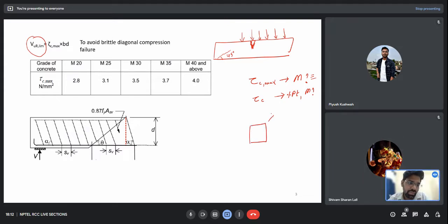Yes, yes. So mainly the principal shear or the maximum shear usually occurs at 45 degrees. That's what you are trying to say. Yeah, that is correct. So maximum shear usually occurs at 45 degrees, and that is the reason we have diagonal cracks like this. That is fine. You can relate with that.